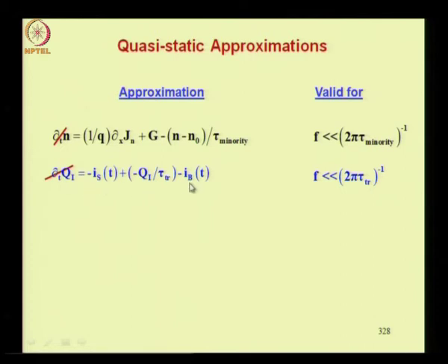Now this kind of an equation is useful, for example, in a MOSFET. So here let me explain what this equation is. This term is the source current into the source terminal. This term is the bulk current, and this term is actually the drain current under steady state conditions. So we have used the transit time concept to write the current.